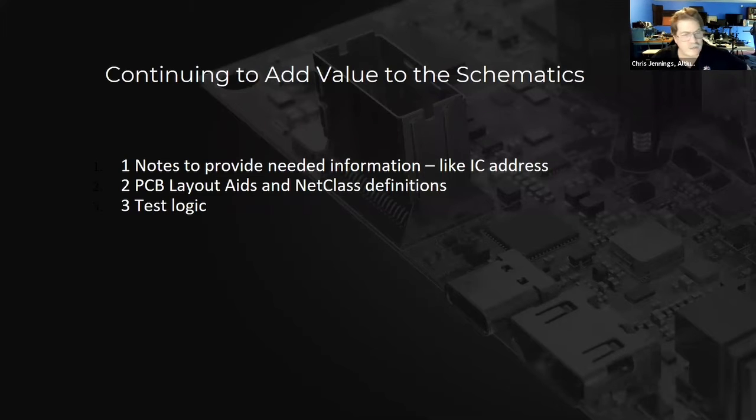One of the other things that doesn't often get thought of until it's too late is adding test logic and/or test points to your design. That same design I was talking about, the array processor, 25% of the parts count for each of the boards in that array processor was test logic.